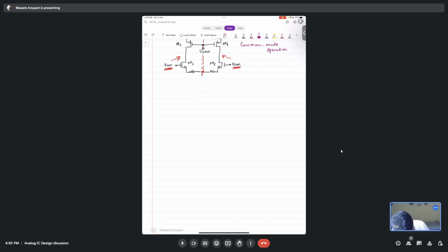If you divide R equally and you are making a parallel combination here, what should these individual values be? 2R, right? If it were series, it would be R by 2. But here there was a single resistor of R, and you have divided it into two resistors and connected them in parallel. So individually they should be 2R, so that after combining this becomes R, right?